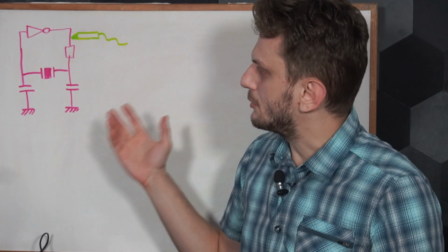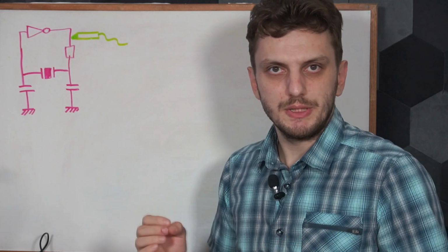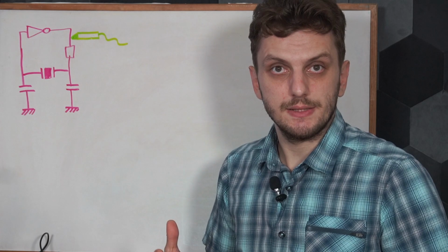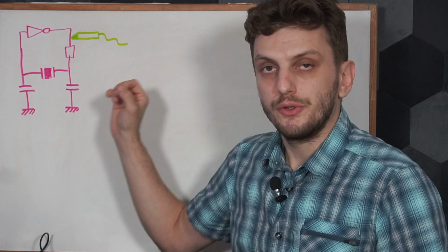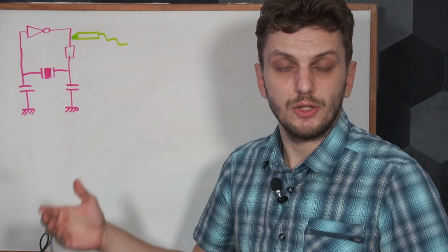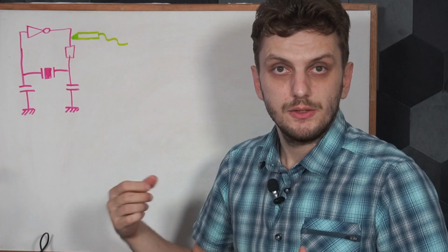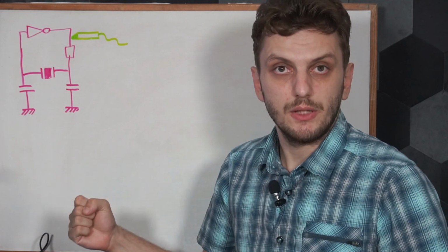So as we discussed in previous videos on the crystal oscillator, this circuit is extremely sensitive to added extra capacitance. So most literature sources will agree that the probe that you're using to probe the oscillator needs to have 2 picofarads or less of capacitance, so that you don't affect the oscillator functionality and, well, the measurement outcome.